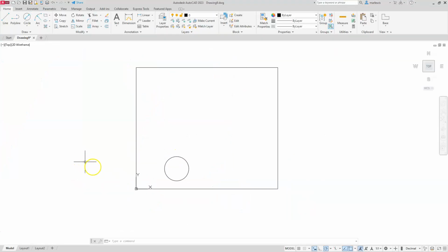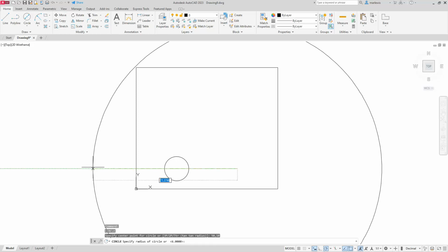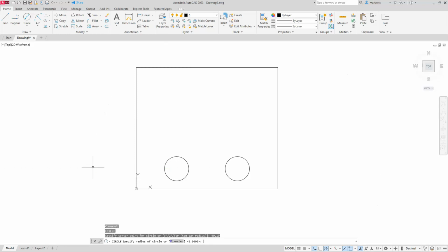Alright, so back in CAD, I'm going to take my hand off the mouse since I don't need to move it anymore. I'm just going to hit the enter button, and that's going to take me back to the last command I did. I'm going to do the circle that's to the right of this one, and that one has coordinates of 50, comma, 10, enter. Then it's the exact same size circle as my last one, so just hit enter.